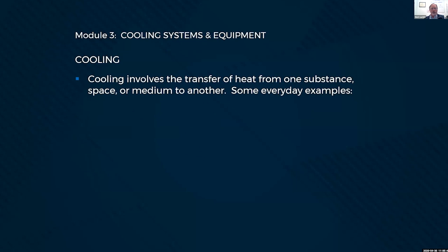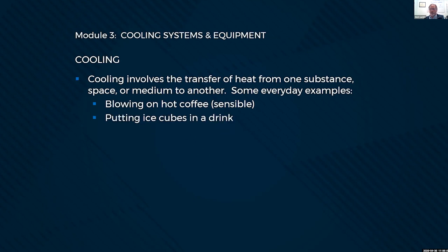So cooling, quite simply, as I said, is the transfer of heat from one substance to another. A couple of examples: you blow on your coffee, you're transferring heat from the coffee to the airstream that you're blowing across it. That's a sensible heat transfer, primarily by convection. You drop ice cubes in a drink, you're doing latent heat transfer, conducting that heat into the ice cube and making it change state.